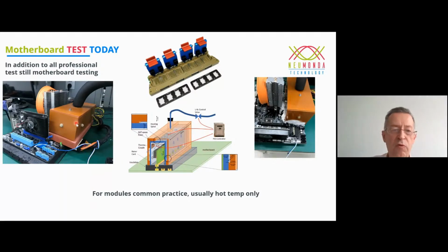Then the operator puts on a microclimate chamber, you test it for 20 minutes, and then you take it out to improve quality. It's difficult for component testing because then you need such clamshell sockets. You have to plug them in manually. Then it's like a memory module: you plug it in and test it. So for components, not really a good solution.